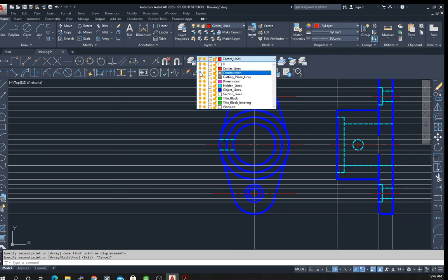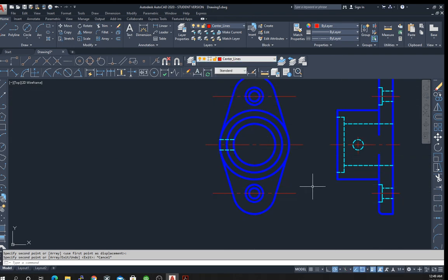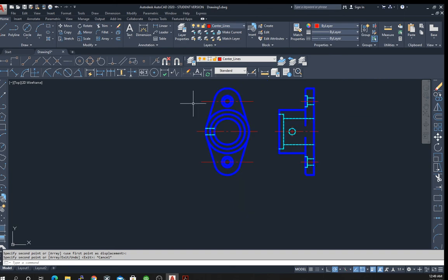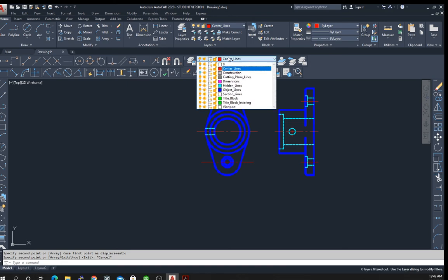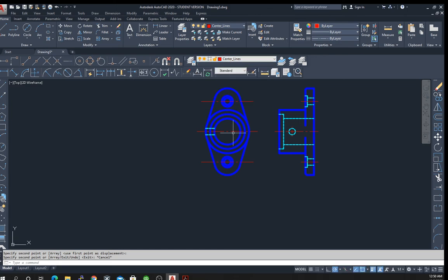So now if we turn off our construction lines, we can see what we have, see what we're missing. Now, we probably should add a center line here just because it looks goofy. It looks like it's missing something. Although it does turn out, we're going to overwrite that and we're not going to see it once we're done. And we don't so much really need to have the construction lines in to do that, because we can start directly at the center.